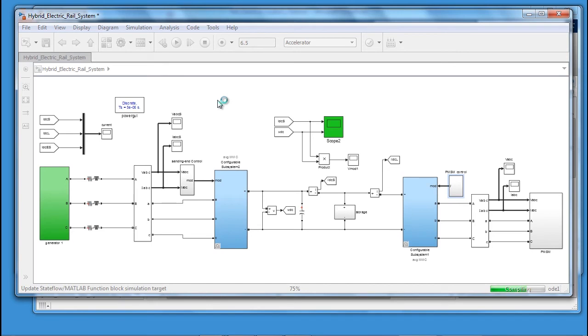As you're going through what you might call the design cycles, you really want to keep the fidelity of the model as low as you can. So average value models of the converters, just a functional representation of the storage device. But you still need to be sure that you're getting the characteristics in that you need. So having the harmonics represented through the average value converter is definitely an important thing to have. And we also want to be sure that we're modeling scenarios that make sense and getting the information that we need to make engineering decisions on the full system.